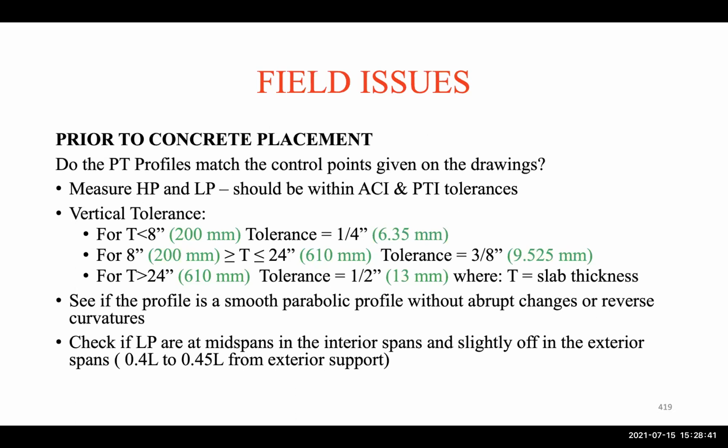Now we'll talk about some of the field issues. Some of the things that we've been talking about, cracking issues and field issues, and we talked about execution of your drawings in the field, whether that is accurate or not. So what things to look for, and some of the field issues that you have to see. Do the PT profiles match the control points given in the drawings? The tendons go in profiles, so we set the profile for that.